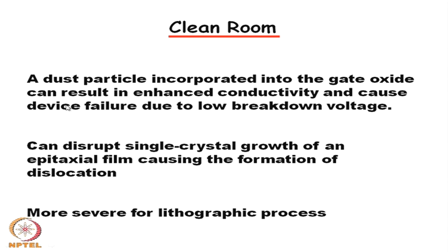A clean room is a room free from any dust particles or particulate matter. The problem with a dust particle incorporated into the gate oxide is that it can result in enhanced conductivity and cause device failure due to low breakdown voltage, because it acts as an impurity, or it can disrupt single crystal growth of an epitaxial film, causing the formation of dislocations. The presence of particulate matter or dust is severe for the lithographic process, as we shall see later, where a clean room is a must.